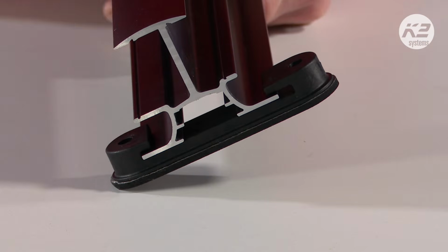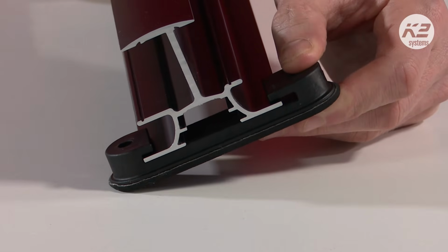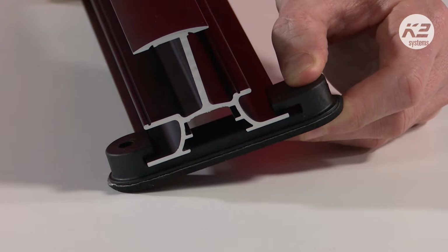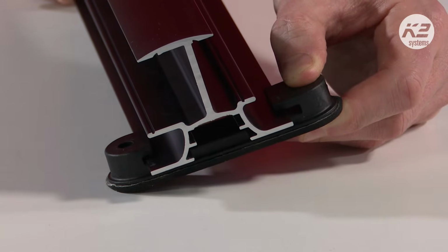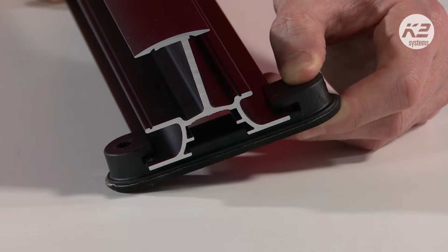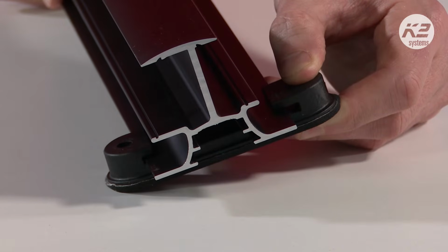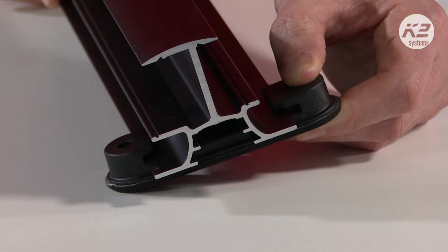And we do this a number of points along the roof, right? And the panels are now fixed, and they're not going to come out off the roof. There is a potential for them to slide this direction, right? But this is wanted. Right? This is allowing for a little bit of thermal expansion, and as the rails expand, right, they're not going to put the stress into the roofing itself. They're just going to slide slightly through.